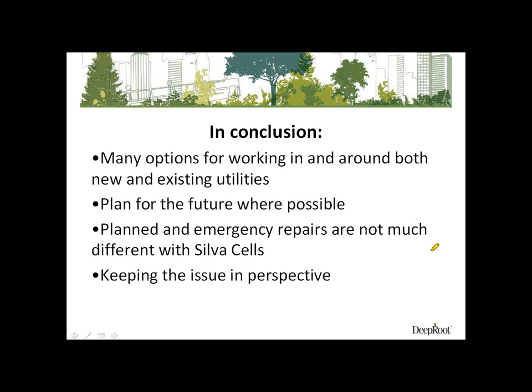So you have people, a good-sized person, an adult walking over soil that's fairly compactable soil. That's roughly in an 8-inch uncompacted lift. So sometimes it takes 2, sometimes it takes 3 lifts to get up through one frame. Okay. And what kind of surface loads can the system support?